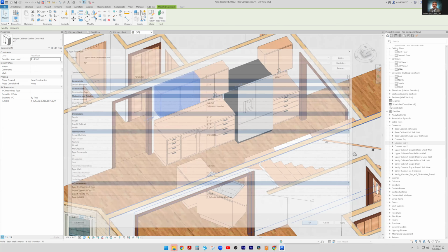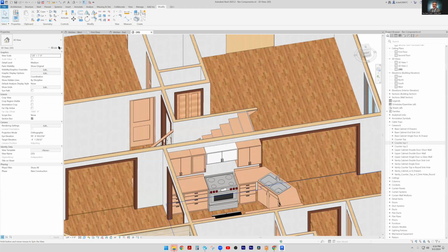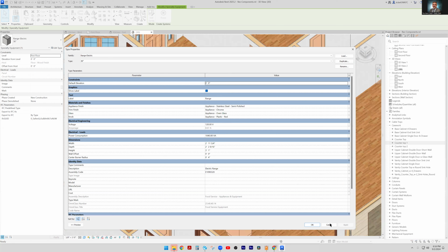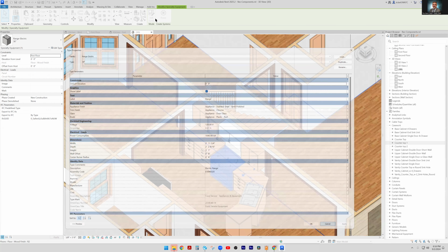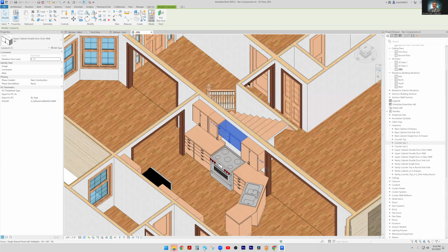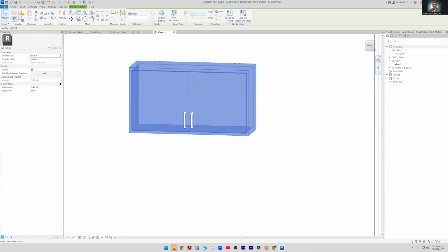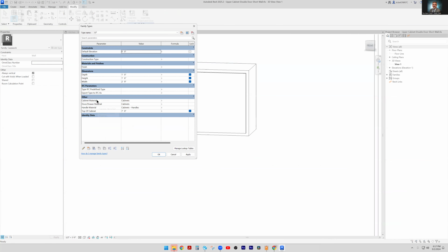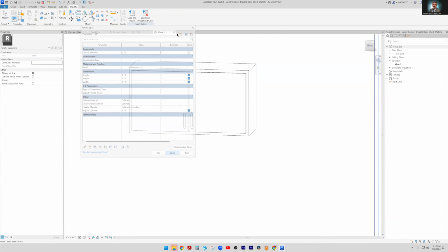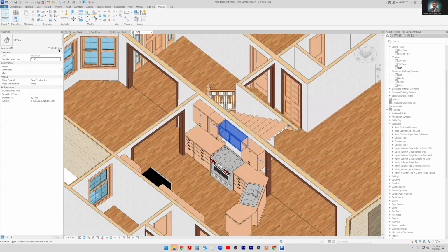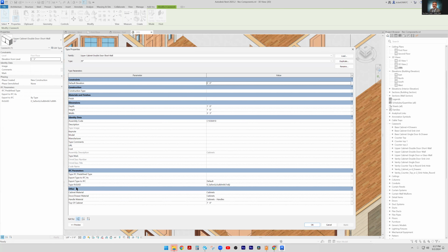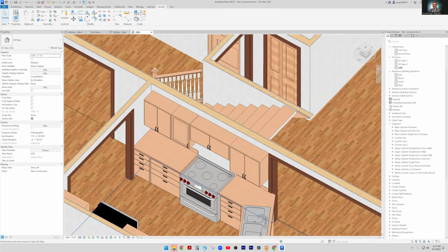So pretty decent. Sometimes in the appliances, you can change material colors too. It just depends on if they've supplied it, and they have. So you can go through there and pick out something if you don't like that. This one doesn't have it to begin with, because they didn't take the time to select this geometry and give it a material. It says it does, under the other category. So that's just me looking under materials for it. It seems natural to find it in the materials category, but somebody put it in other, so it's down here. And you can see that it's cabinets, plural. That's why it's not colorizing the same way. I gave it cabinet, singular, and there you go. So that's how you do it.